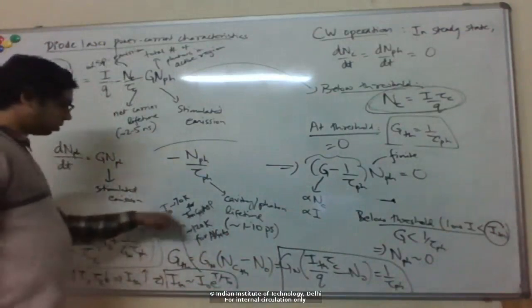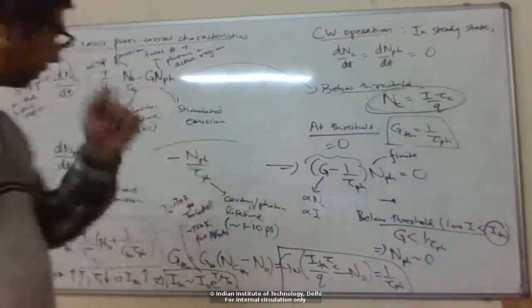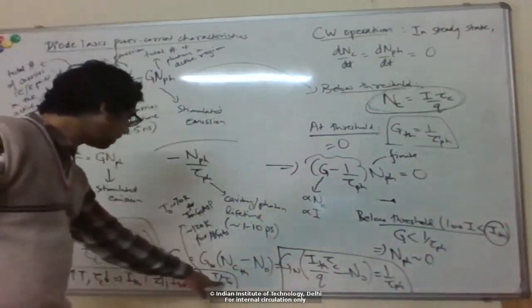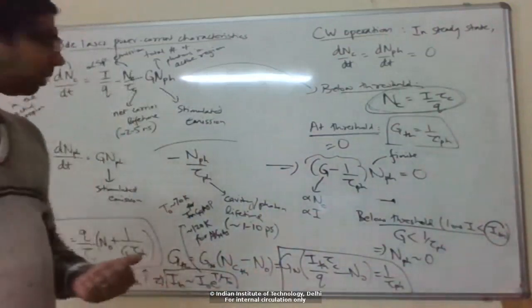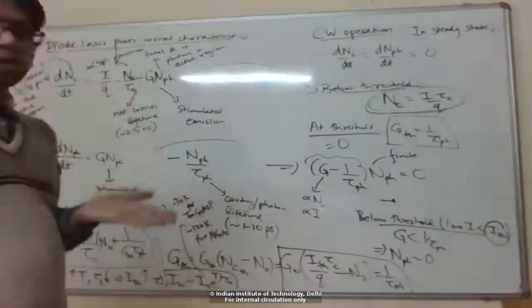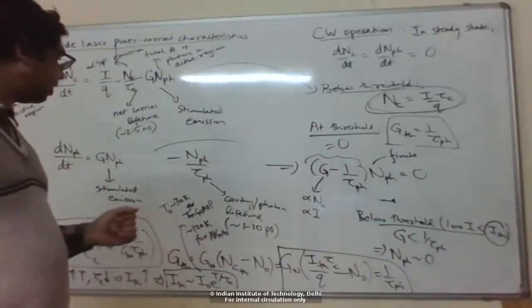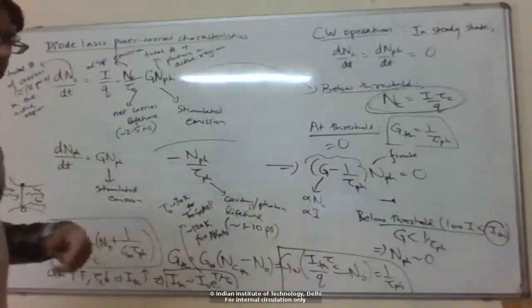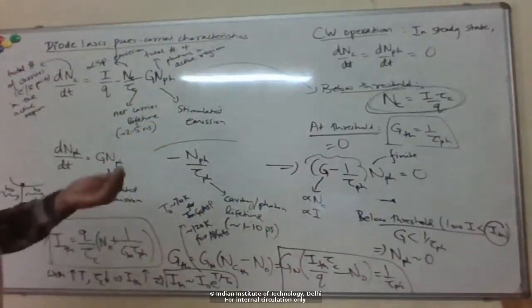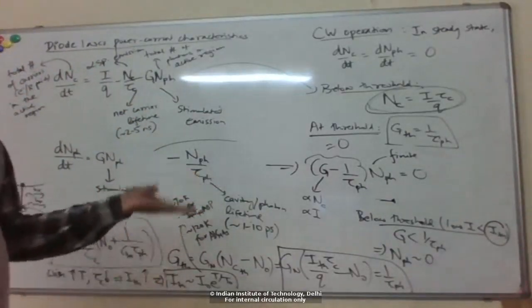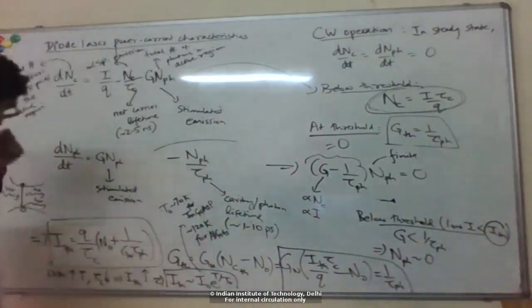But you can see that for telecom devices, temperature control is very important. This is not to say that we operate at 70 Kelvin, right? This T0, this constant, is 70 Kelvin. Typically we operate somewhere near room temperature, but the point is that you need to control temperature. Because if you don't, if you just let the device free run, then even just as the device operates, it generates heat due to, again, these internal losses, etc. And then temperature starts increasing, and the device starts degrading, and then with this positive feedback loop, the device can fail. So temperature control is very important.